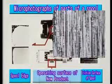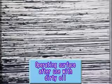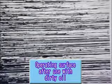Let's first take a look at a new spool. This spool has vertical processing scars in the circumference direction made during the manufacturing process. The spool used in a dirty oil environment has severe horizontal scars in the operating direction. The scars are so deep that it is almost impossible to see the processing scars in the circumference direction.